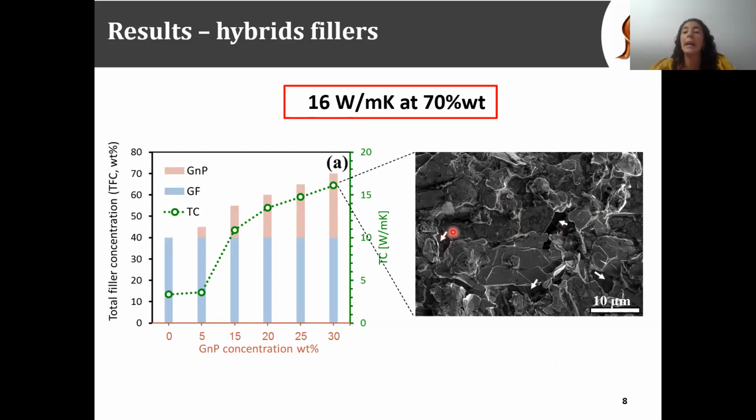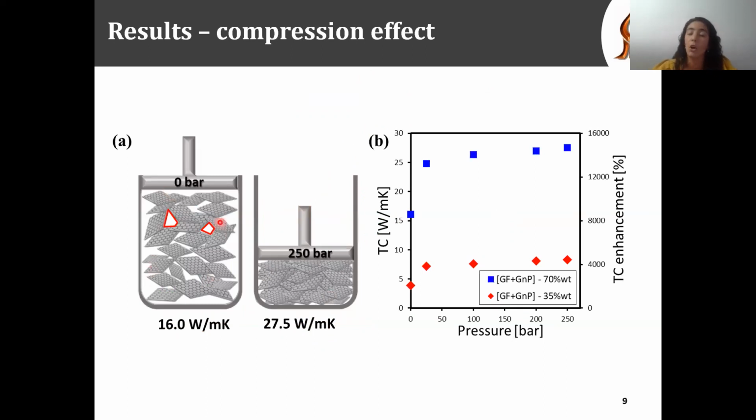And since air voids are a failure point in the composite, since air is thermally insulating, their appearance may affect the thermal behavior of the whole composite. Therefore, in order to enhance the thermal conductivity much more, we decided to decrease the number of air voids. It means that instead of casting the composite under atmospheric pressure, we decided to pack them together by compression.